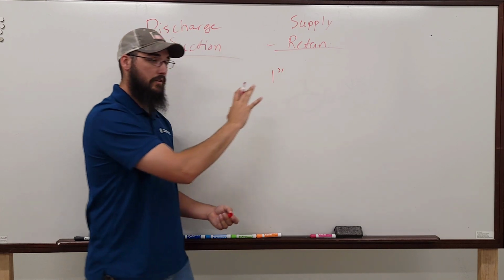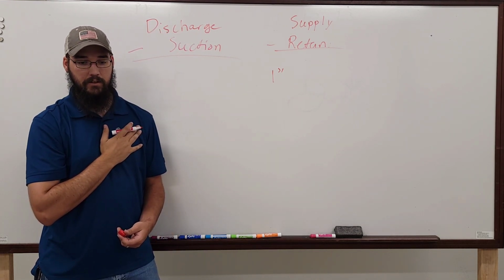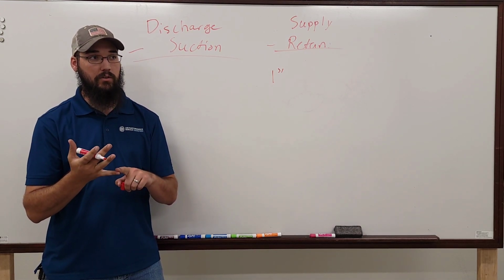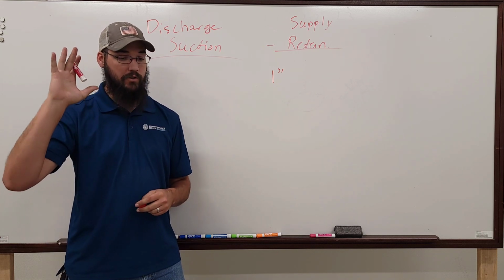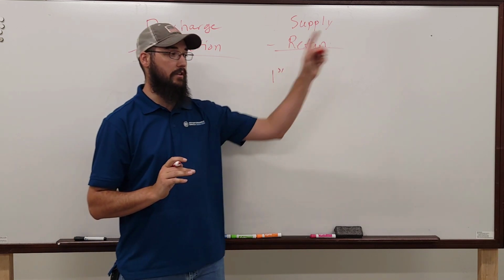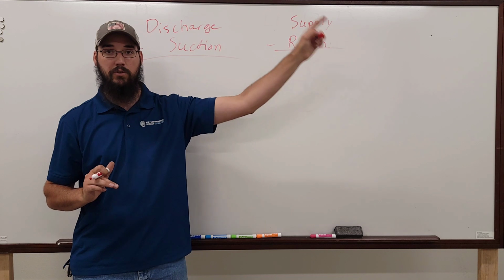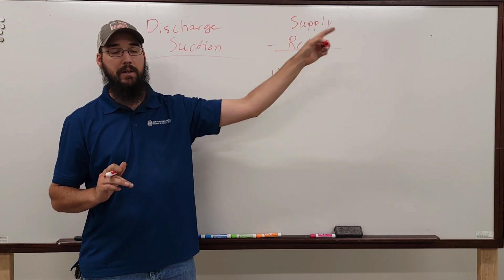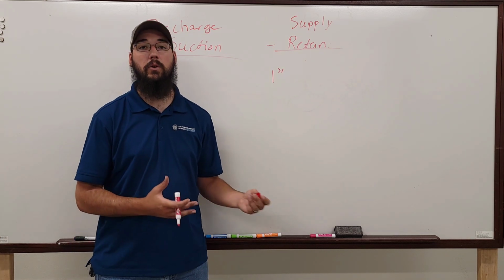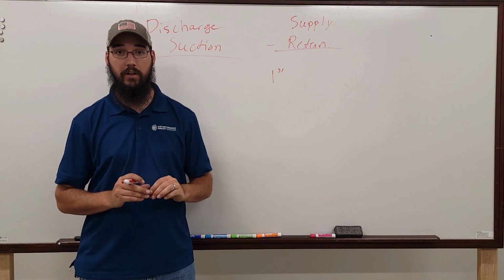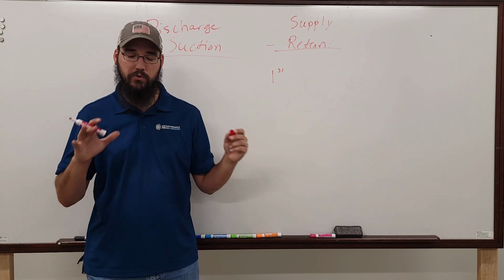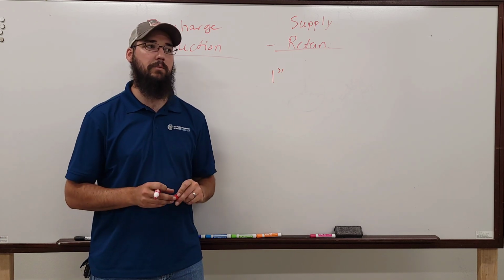The only reason, in my opinion, to go more than 1 inch on any duct system is either leaks or poor design. I will vouch, there are systems out there that are very poorly designed, and the only way those engineers can get the proper amount of air to the furthest boxes, which are your main problems, is by ramping that static up to 1.25 inches, 1.5 inches. They don't have another choice. So those scenarios do exist. They're not ignorant, it's just what they're dealt with. But the vast majority of the systems out there, that is not going to be a requirement.